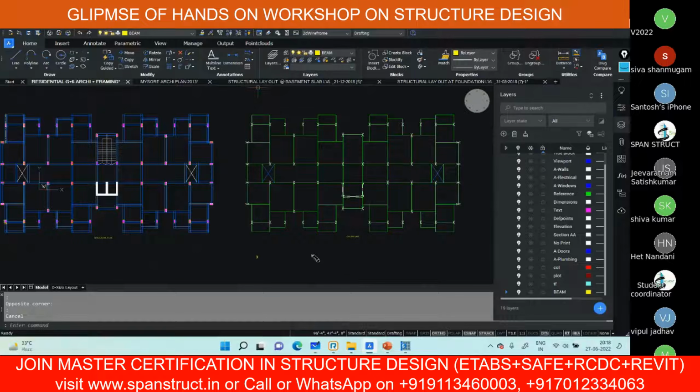Please remember that whenever you convert the structure framing plan into center lines, don't take the column center line, take the beam center line. I will explain further in the class why we take the beam center line and not the column center line. And please remember we are doing this only for creating the mathematical model in ETABS.